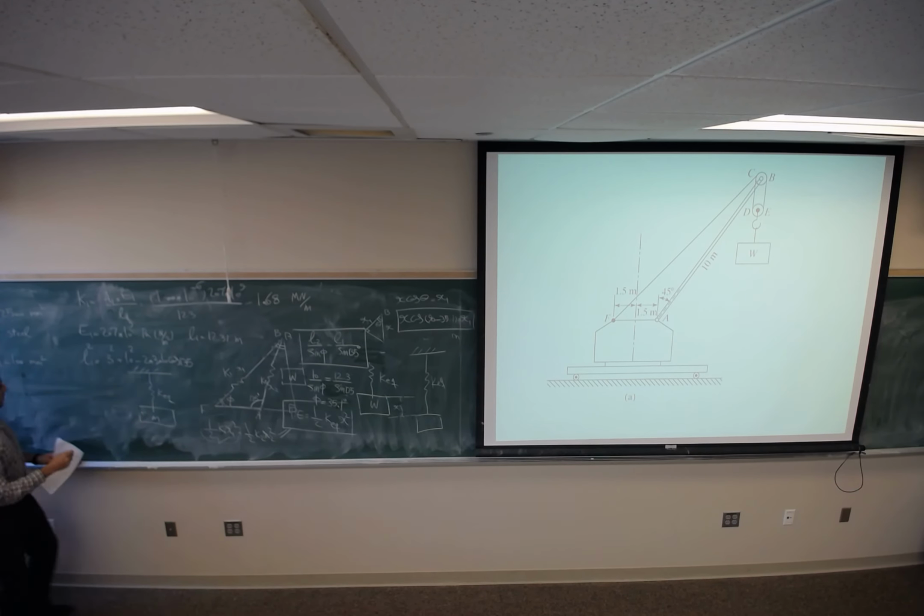Second term, half of K2, would be A2 E2 divided by L2. A2 is 2500 times 10 power negative 6. E2 is the same material, made of steel, and L2 is 10 meter. K2 is 51.75 meganewton per meter.